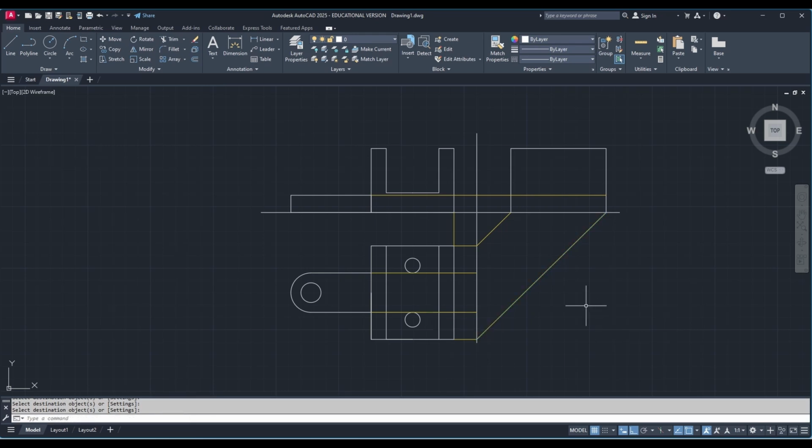After that I'm also projecting this arch portion by turning off the ortho and making it above the XY line and pressing tab on the XY line and then typing 45 and hitting enter. By pressing the tab, the option will change from linear dimension to angle. Instead of projecting like this, you can also directly type the values and get those. This is just for easier understanding of where these dimensions are coming from.